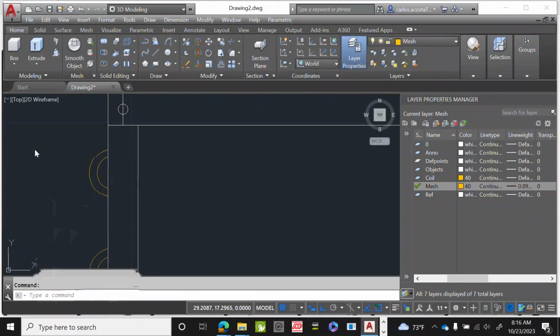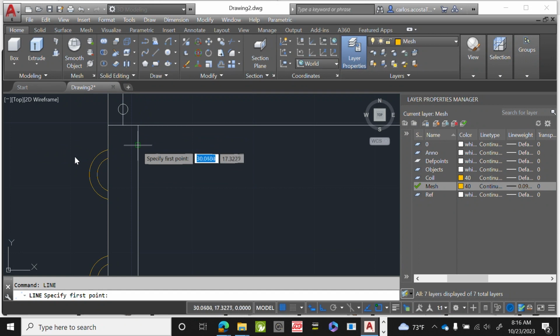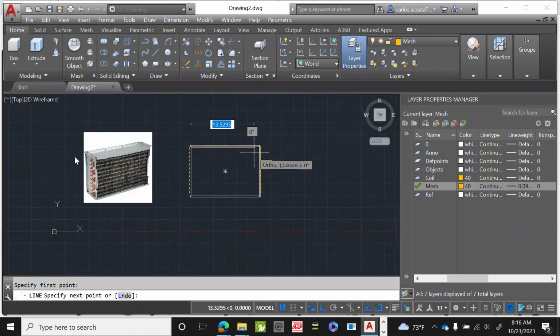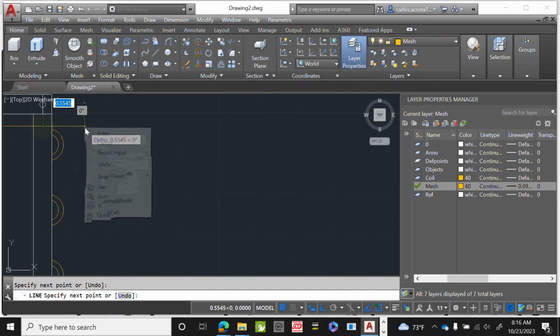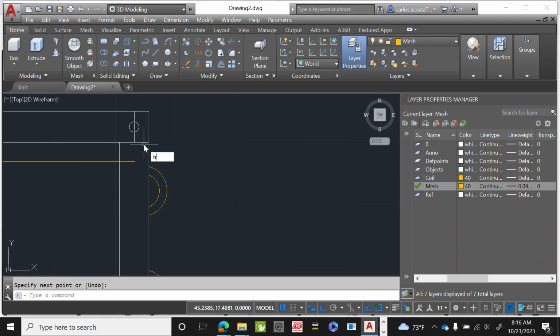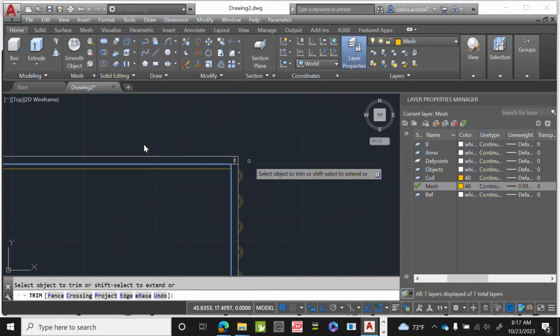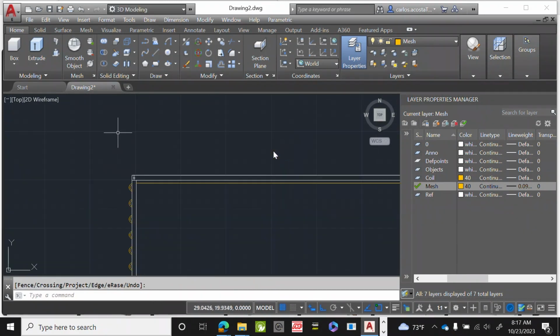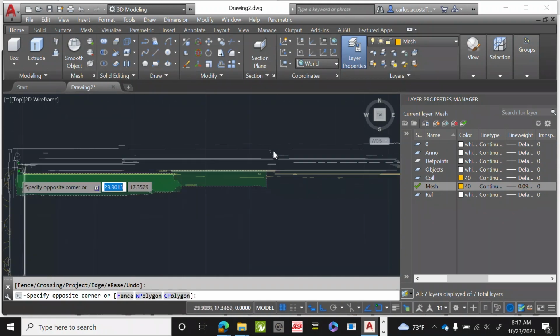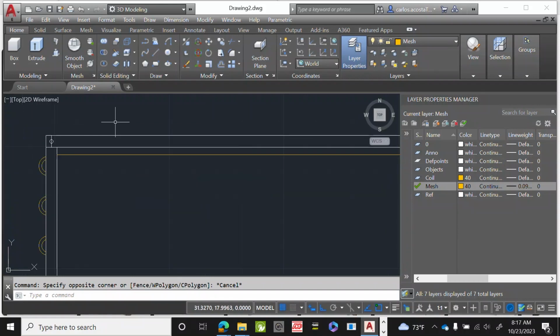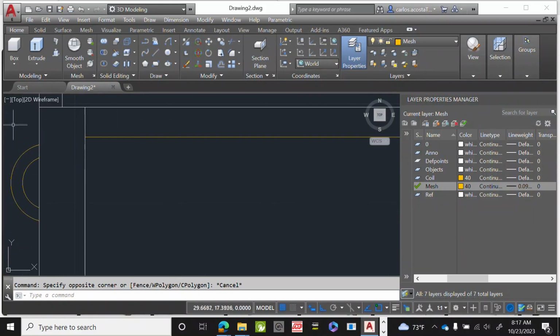select that layer, repeat line, we're going to find the endpoint of this line, which is right here. Okay. Just to make sure we have it, go across, enter, then we can do a trim and use this trimmer for this line. All right, we got it. Okay, so if you notice, this line was more or less... actually, I didn't do it right because I didn't need to use that baseline now that I think about it.